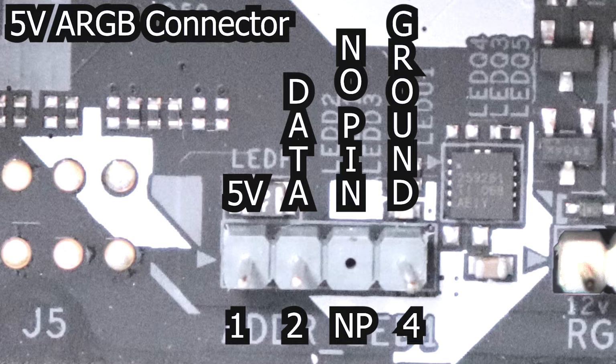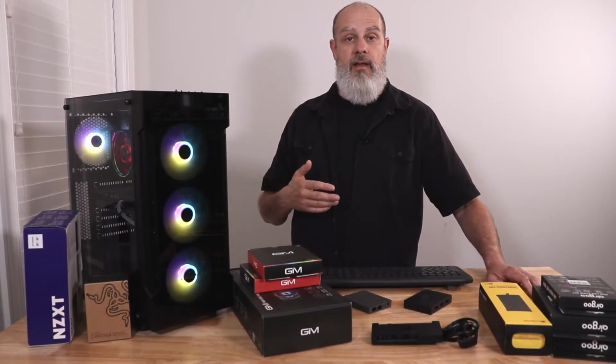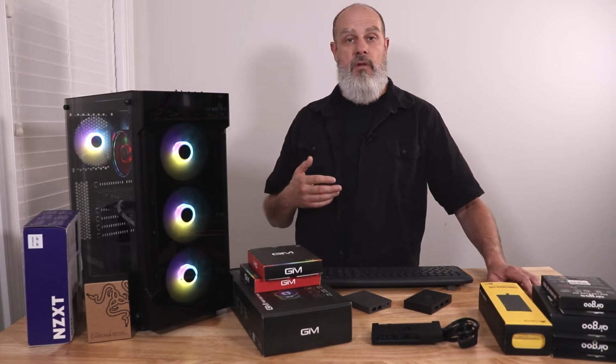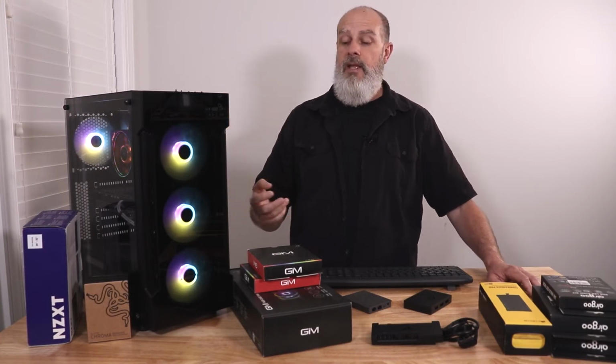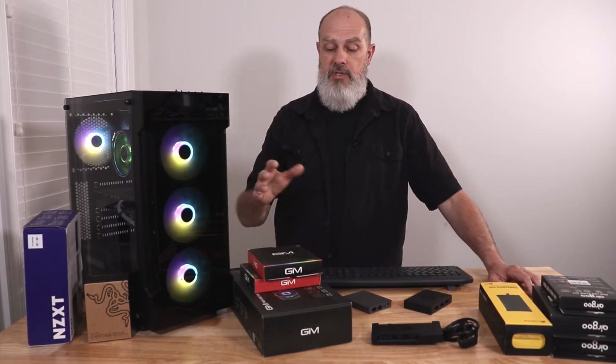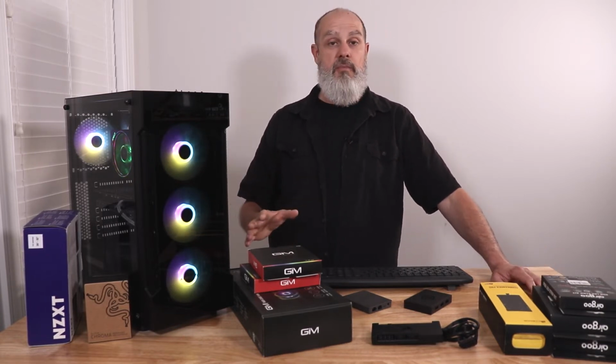Now, how this works is we apply voltage across the string of lights, and then we apply a data signal across it because we can talk to each WS2812B controller individually. We know where they're all at, and through that we tell it what voltages to allow to each individual RGB element of that package, thus setting the color of that particular light, and so on and so forth. And we can send all that data down that port to each individual chip, thus we can get all these fancy customizations, all these cool lighting effects. And so that pinout is pretty standard. I would say most of the stuff out there is going to have that particular pinout. Now there are exceptions, and we'll talk about those.